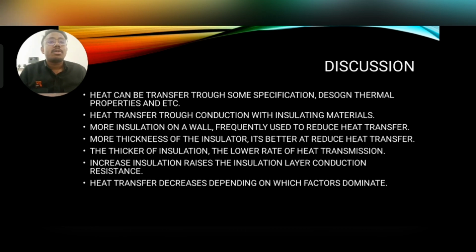Important inputs are the operational and emission temperature, diameter of inner wall and outer wall, and unit cost. We also limited the procedure for determining the most effective insulation type and thickness. Heat transfer and economic analysis are required to determine the optimal insulation thickness.